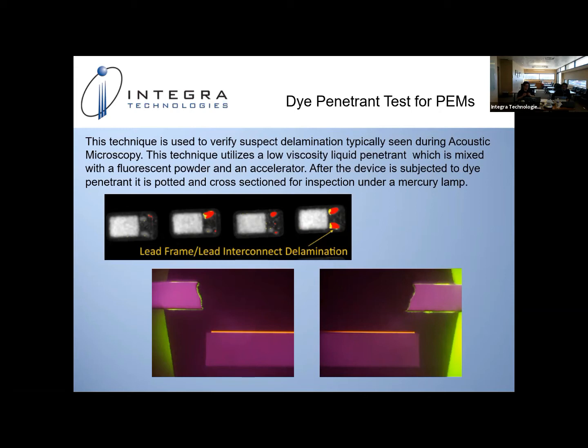In cases, SAM is going to show delamination on the top surface of the die. There may not be a path for moisture, so it may not be a concern, but it may be a concern for the packaging folks and how it's going to act in reflow. But with a lot of the qual testing that Sultan and these folks do, if electrical testing is ruling it out after several quals and several tests, the data is there and a better decision can be made. Absolutely. I don't know if you want to chime in on that.